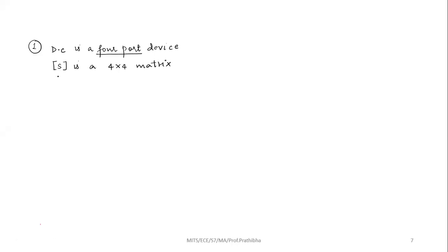Now with all the diagonal elements, that means I'm making my first condition here, they are 0. What is the meaning of this? Anybody in the chat box? What is the meaning when I put S11, S22, S33, S44 as 0? Perfectly matched, says Vishnu. Yes. So S11, S22, S33, S44 are perfectly matched, so there is no back reflection from them if you give it from the same input. So that's the first point.